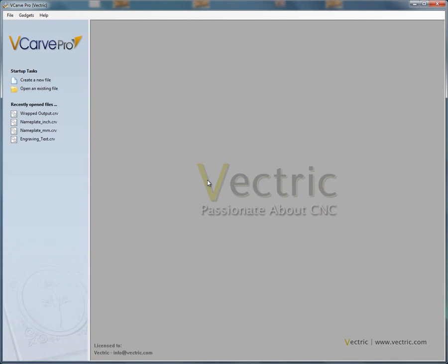Let's take a look at the interface for VCarve Pro and explain how you use the software to draw and toolpath projects. When you run the software, you'll see listed down the left side of the screen options for creating new projects or new files, and opening existing files. There's also a list of most recently opened files, so if we clicked on one of these names, these files would automatically be opened here in our two-dimensional view.